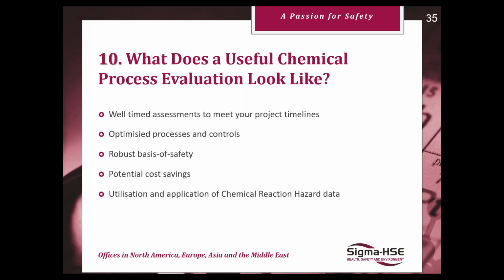heat evolved, how is the process and the plant going to need to be designed and set up to run this process? You're going to need to make sure that you have sufficient cooling capacity or scrubbing capacity or venting, but having had the data and the knowledge, you'll know what you need to expect, and you won't be oversizing for these kind of things.